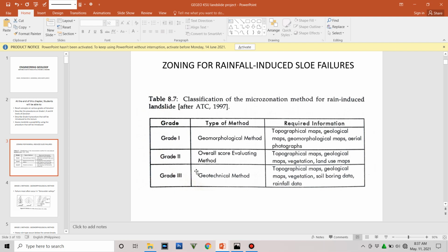In here, we are getting closer to a more rigorous survey, but this method was developed by many researchers, wherein it's like you're scoring a beauty contest. Okay, so we'll just have to use some tools in scoring and a little bit of arithmetic to solve for the factor of safety. The factor of safety is the determining factor in terms of the susceptibility of the landslide.